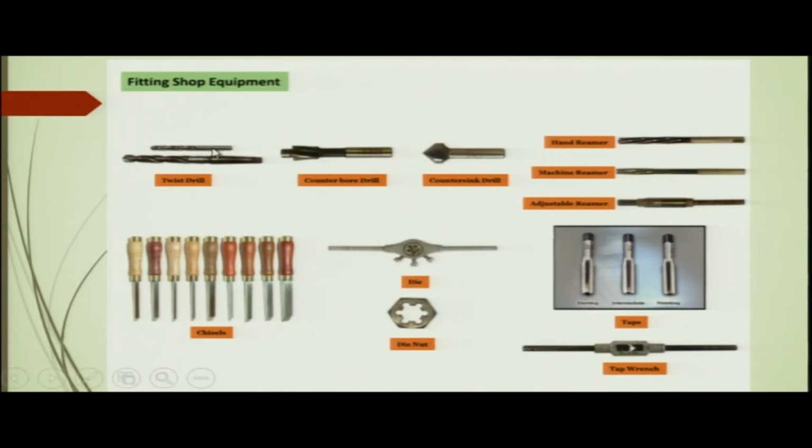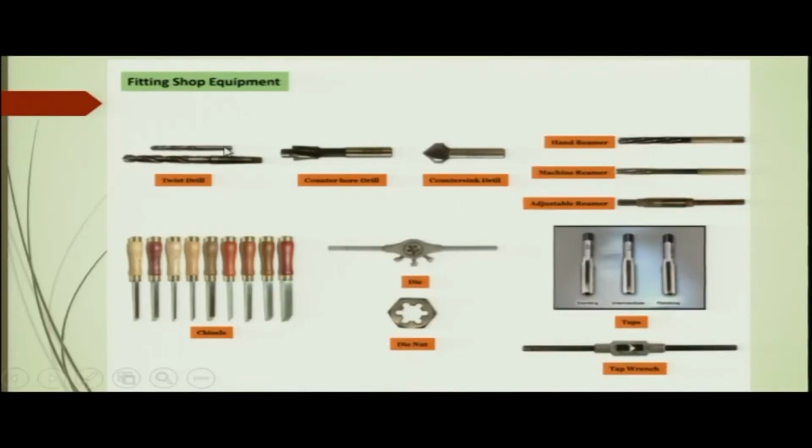In this case, the torque carrying capacity of this drill is less because the diameter of the drill is less, so the hole that will be drilled will not be of larger diameter, it will be of this diameter. Therefore, the torque to be applied for drilling the hole will not be so high. So the shank is made as a cylindrical shank, and that shank can be mounted on the holder not through the Morse taper, but through some other mechanism applied on the cylindrical shank.